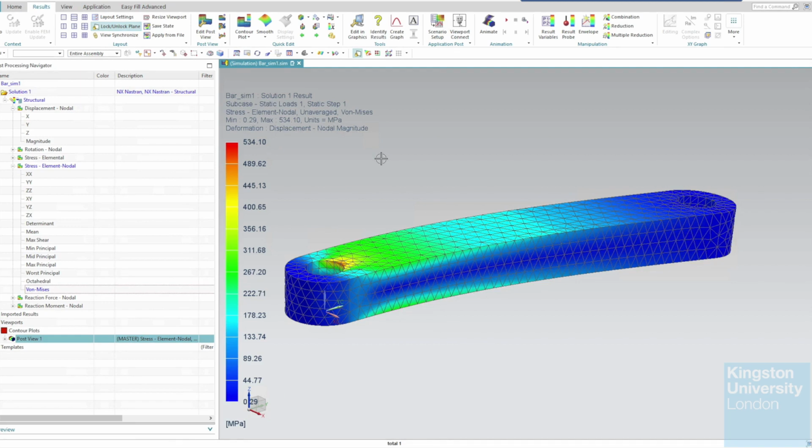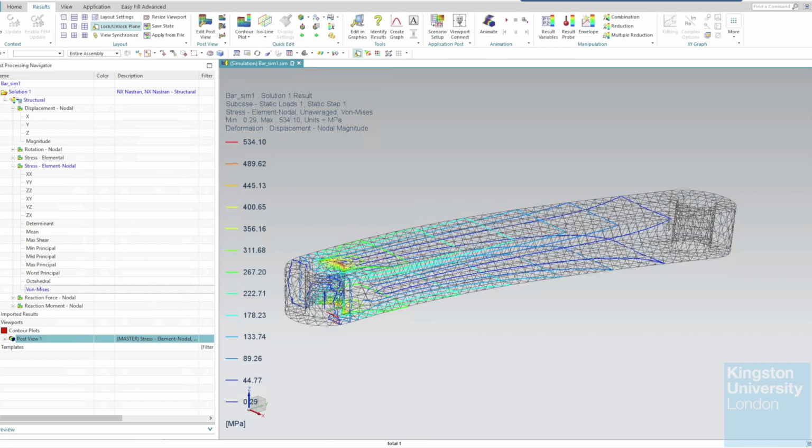And that's the stress that I have over there. So if I want to change here, this one is a smooth. If I go to the quick edit, I can change it to the banded, so I can find out the exact area that the levels of stress has been changed in here. I can even make it as a line, so I can see exactly what line is the difference between the stress, for instance, in here, or even displacement over there.